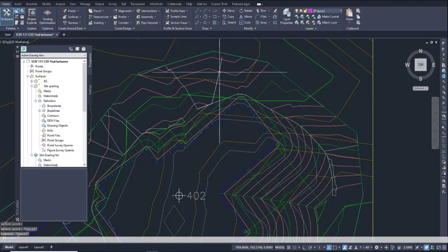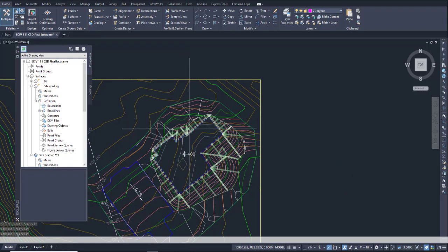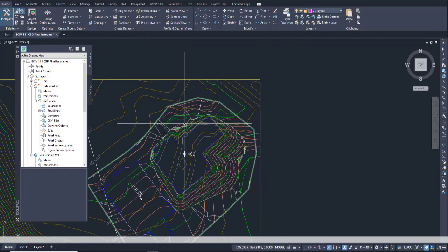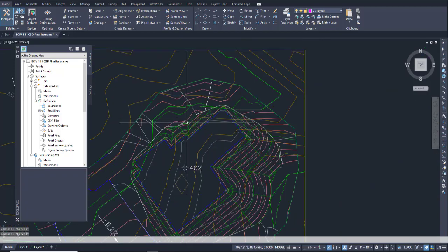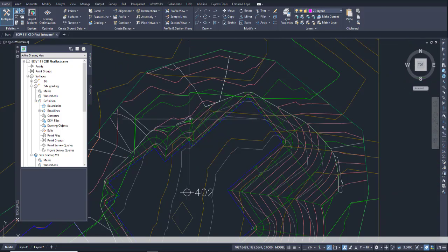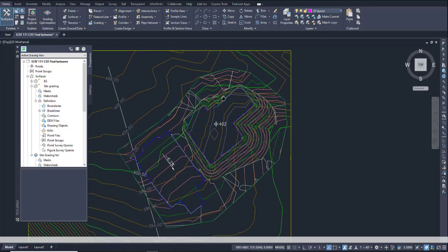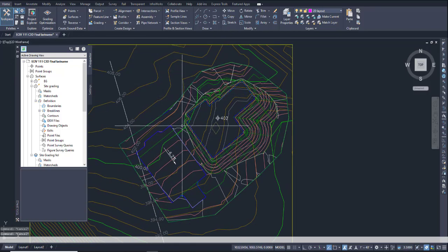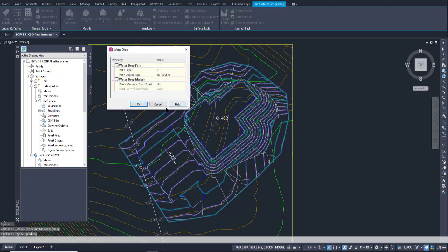And you'll notice here, the water comes in here, and you see this enclosed polyline for the contour. That's actually a depression there. So if I were to do this design, I would have to put a storm drainage box here. Okay? So, and that's exactly where it would go. In fact, I might even refine this grading to maybe make a low area a little bit further out here. Okay? To force it to be a little lower. Okay? I can further do some analysis of where this grading is. It's a nice little thing here.